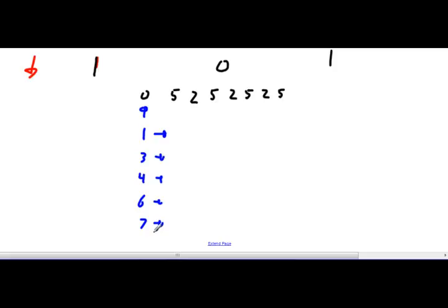Okay. Enough of that. But that's how you'd have to do it. You'd have to go and say, the J is this, the K is that. What's going to happen on the clock pulse? For this one, 111 would be the answer because it's constantly being set. It's always set, yes. So the Qs are always high.